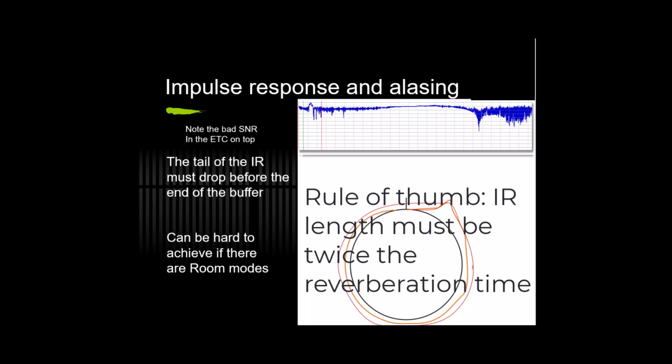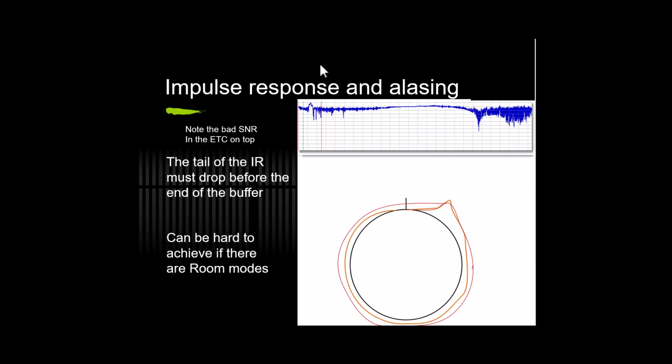One of the problems has been that many users use real-time transfer function, which only provides around 1 to 2 seconds, and therefore you get this aliasing problem. Therefore I recommend to do the room mode detection and apply the filters before you do any other measurement for equalization and delay alignment of the system.